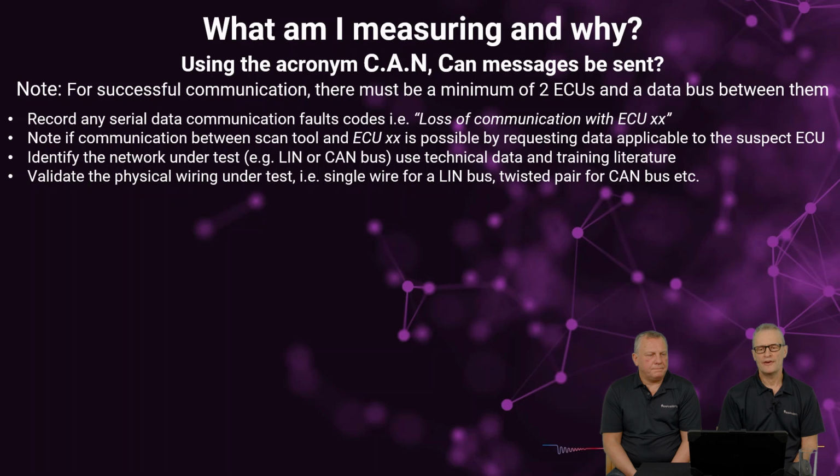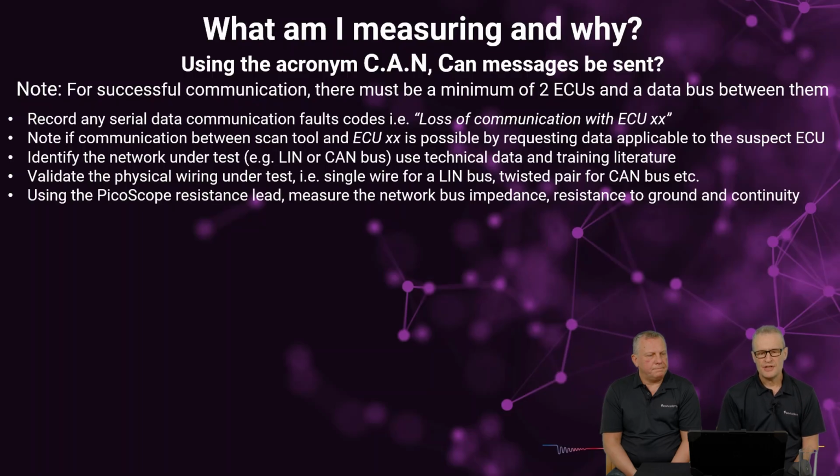Validate the physical wiring under test: single wire for LIN bus, twisted pair for CAN bus, etc. Wire colours as well. Using the PicoScope resistance lead, so remember the acronym CAN, can messages be sent. Measure the network bus impedance, resistance to ground, and continuity if necessary.